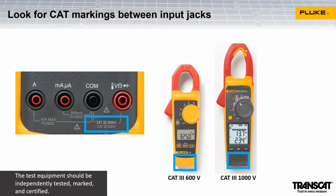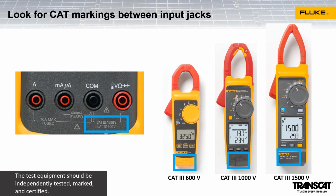So we could use that on both residential and commercial and industrial rooftop systems that go up to 1000 volts. And then we have our 393 clamp meter that's rated for category 3, 1500 volts. So this could do residential, commercial, industrial, and utility scale systems up to 1500 volts.